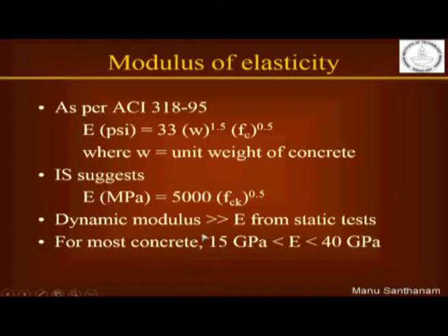Okay. So, the dynamic modulus is the modulus which we find from other tests, not loading-based tests, like ultrasonic pulse velocity and resonant frequency. There are different tests from which you can actually measure the dynamic modulus of concrete. Those kinds of testing give you moduli values that are much greater than what you get from static tests. Okay, please remember that.